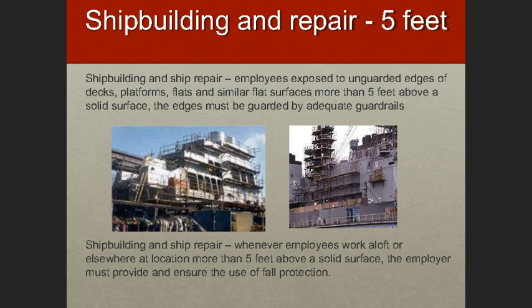For shipbuilding and ship repair, employees exposed to unguarded edges of decks or platforms, flats, or similar flat surfaces more than 5 feet above a solid surface, the edges must be guarded by an adequate guardrail, and the standard there is 5 feet. So in this particular instance, in shipbuilding and ship repair, at 5 feet or higher, we need to look at some type of fall protection system.